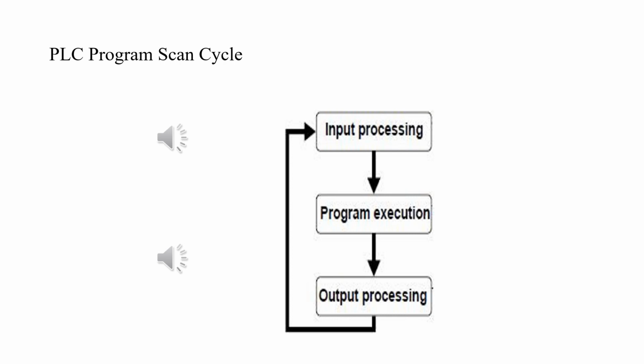To give you an idea of the time of changing inputs in real time, if we have push buttons, a push button pressed by a human being, this pressing will last between 200 and 300 milliseconds. So this is a long time compared to the very short time of the program scan cycle.